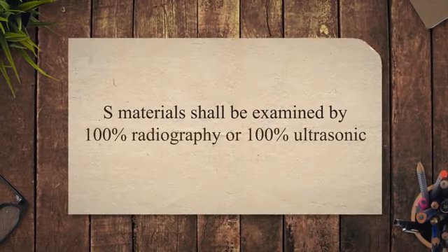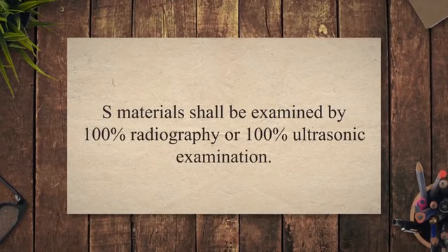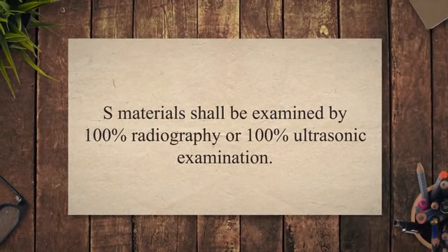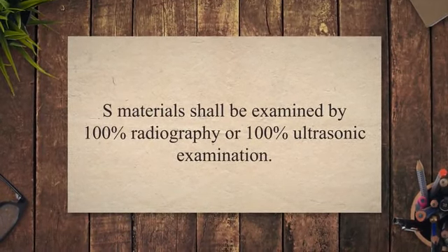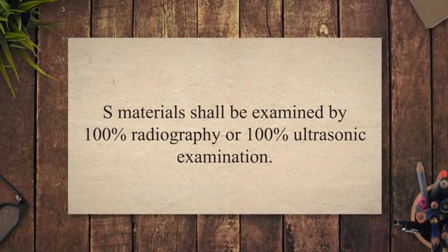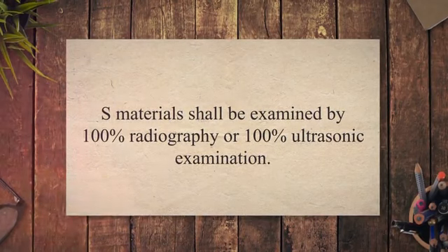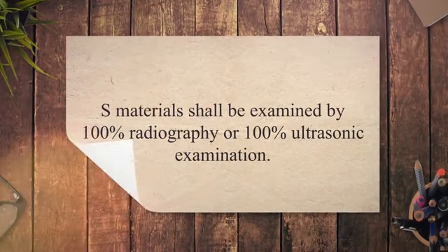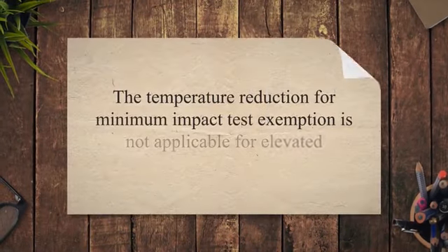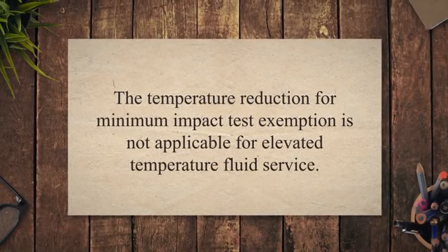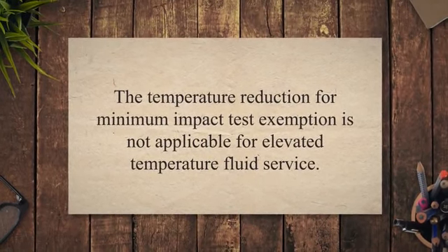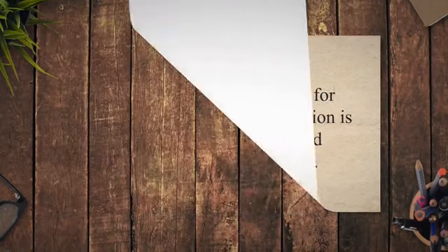In elevated temperature fluid service, all longitudinal or spiral (helical) seam welds in P-No. 4 or P-No. 5 materials shall be examined by 100% radiography or 100% ultrasonic examination. The temperature reduction for minimum impact test exemption is not applicable for elevated temperature fluid service.